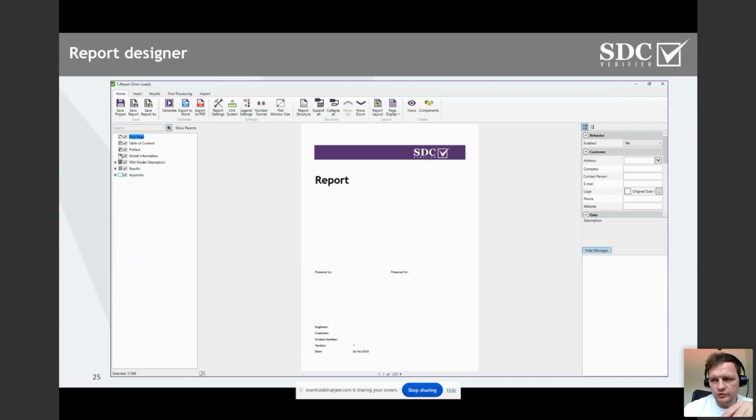So in the same way as we just previewed utilization factors and with plots and table, you can take a look on stresses, displacements, reaction forces, include all of those results in a convenient report of your style. So you define the layout, you define your, if you say, I don't like this purple color and I want my own logo here, you define your template. It's quick and easy to define this layout, and continue generating reports in your style, including general FEA result, code check result, parts of custom documents, and so on.